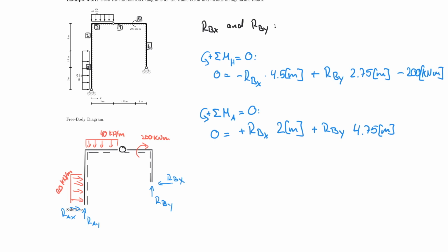Yes, so therefore it's positive. And I want to re-emphasize this, right? Here it's plus plus, whereas here it's plus minus. That seems strange on first glimpse, but keep in mind that because you turn about this point in the first cut, and in the second cut you turn about this point, this RBX takes a different rotation. It turns clockwise versus counterclockwise on one of them.